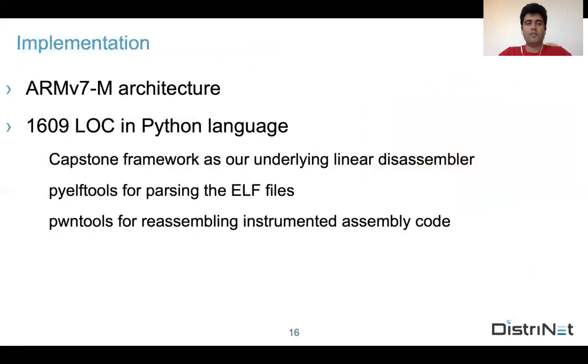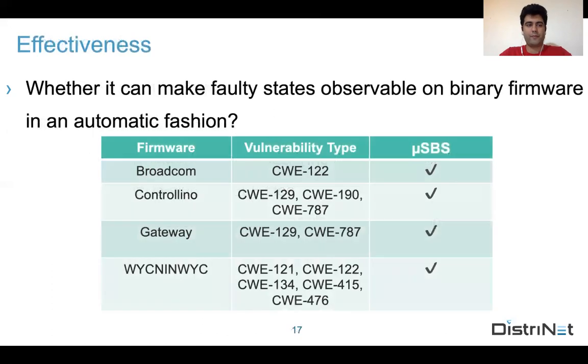Our implementation is focused on the ARMv7-M architecture, which is a widely used architecture for embedded devices. And also we developed our tool in 1600 lines of code in the Python language. And we use the Capstone framework as our underlying linear disassembler, and pyelftools for parsing the ELF files, and pwntools for reassembling instrumented assembly code.